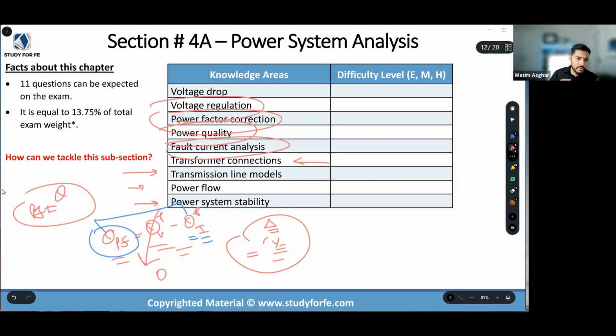and voltage regulation had started making an appearance in transformers, and voltage drop had started making appearance in motors and transformers. And the big thing over there was magnitude only, right? And when we're dealing with voltage drop, use the equations properly, use the phasors, right? And make sure what type of voltage you're calculating. Are you calculating voltage drop line to line, or line to neutral? They're two different formulas, right?